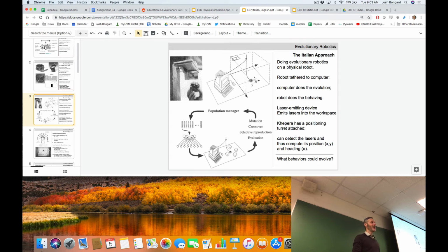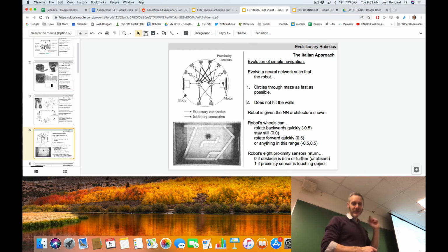Could the robot evolve to stay on the table, given what I've just told you about its sensor and motor complement? As long as it's just an ordinary table, then no, because it'll never see where the edge is. Exactly. We can see where the edge is. The robot can't. So in all the experiments we're going to look at in this course, you need to put yourself in the shoes of the robot, right? You can't see in 3D and color and hear and sense and so on. You're the robot. All you get are these 8 values at one time instant to the next. So you cannot see the edge of the table, which means you can't evolve to stay on the table. You may be able to see and turn away from obstacles that are placed on the table. That's possible, right?